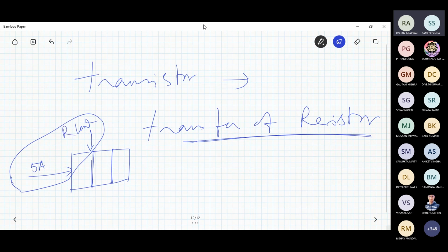Resistance will be low, right? Let us say the input resistance is 10 ohm. I am just arbitrarily assuming. Here I have told resistance is high at the output side. Why output? Because I am assuming emitter, I am injecting a certain amount of current, and the output is the collector side. So collector to base will be considered as output, and emitter to base will be considered as input. In the circuit I will discuss in detail, but preliminarily, because you raised this question, what will be the input voltage as such?